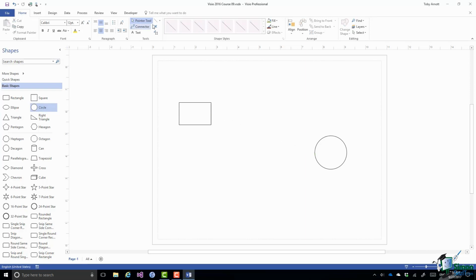And I'm going to do the same thing again, but I'm going to do it wrong. So I'm going to go down here. I think I'll click to this sign, glue to connection point. Yep. Keep the mouse down, drag over here. Now when I get to the circle, instead of connecting to one of the connection points, I'm just going to move around here a bit. And there you can see I've got a screen tip snap to geometry. So I'm going to release the line, and the line now ends there.